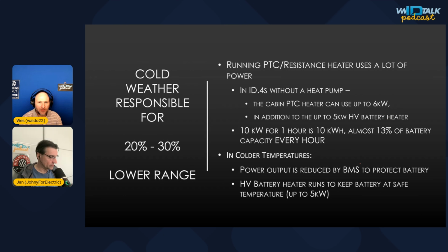Yeah. And in addition, the power output is reduced by the BMS, the battery management system, in order to protect the battery, because at colder temperatures the battery can form dendrites, which could cause shorts if you pull too much power. So they run that high voltage battery heater to keep it at a safe temperature.